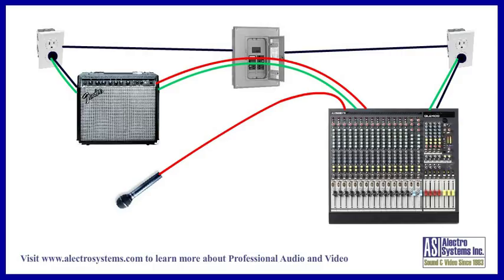One way which often works is to remove the AC ground connection on one of the devices. This way there is only one ground point. Although this is a simple solution, it is frowned upon by the electrical industry. The ground pin connects the chassis of the device to earth ground as a safety feature. If anything happened to cause the AC hotline to touch the chassis, the ground connection would provide protection by quickly tripping the AC breaker. Without this feature, if a problem did occur, anyone who came in contact with the chassis, even through the guitar cable, could receive a nasty shock. Needless to say, this is not a desirable thing.